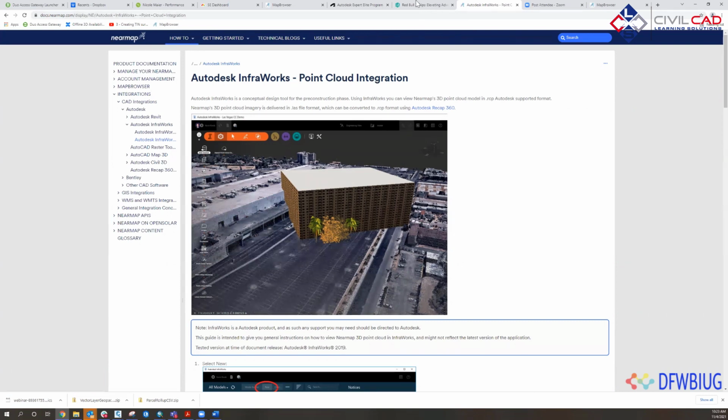Okay, cool. The next question I always get, because when I'm out teaching as a private consultant, I teach Civil 3D, Infraworks, vehicle tracking and AutoCAD, and I tell them about Nearmap. I usually turn off the geolocation tool in Civil 3D, and they see the aerial on a site plan and ask, hey, where'd you get that aerial? Then they ask, what resolution is that? So the vertical, we're capturing 2.2 inch resolution, and on the 3D it's about 2.8 inches. So all of our content is sub 3 inch resolution.